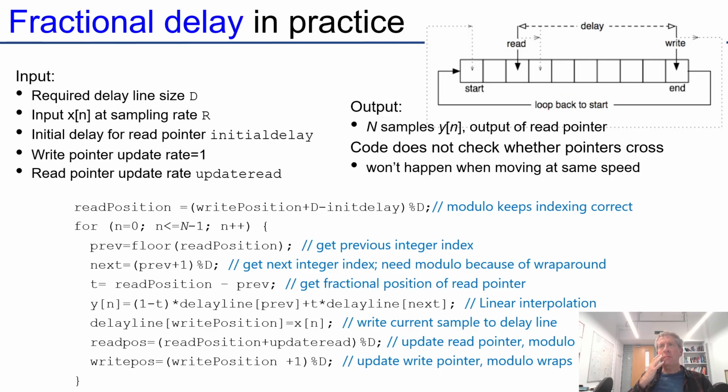So, moving back, how does one work with fractional delay? Recall that with delays, we generally have a read pointer and a write pointer. So what if you want to read a value between nearby values? You do the same thing as done previously, only now you interpolate these nearby values.